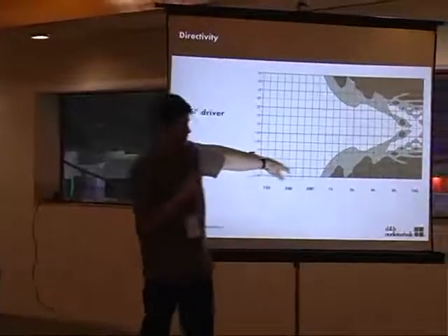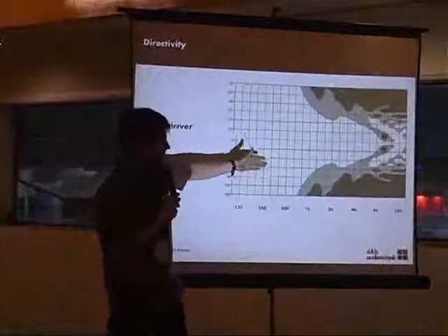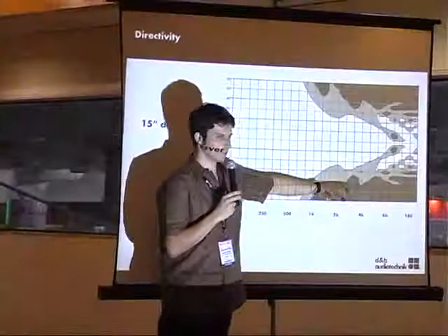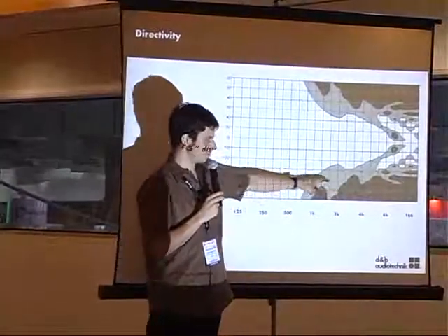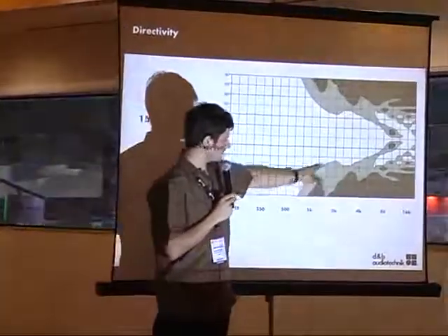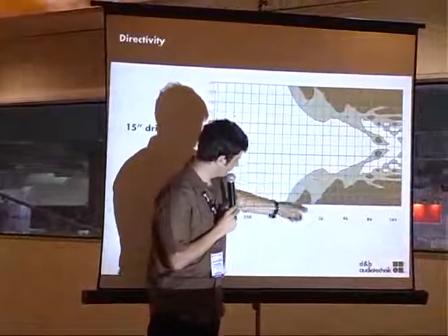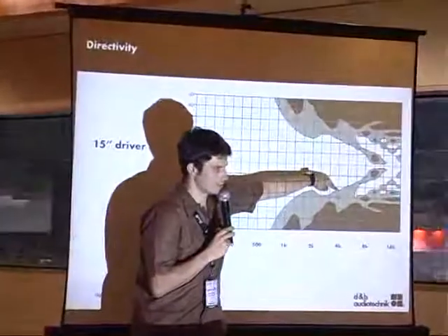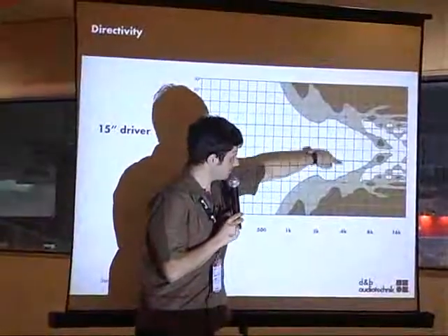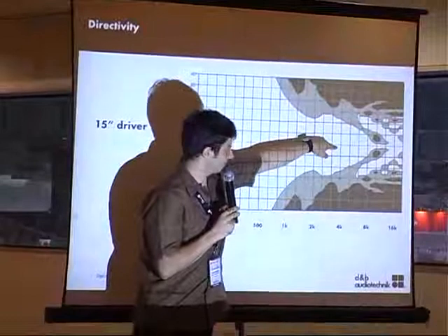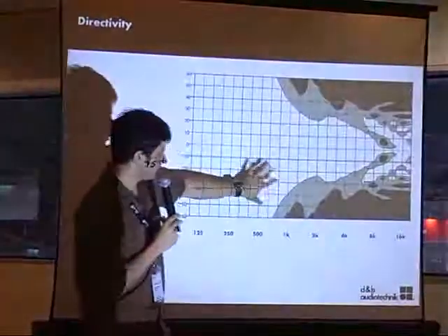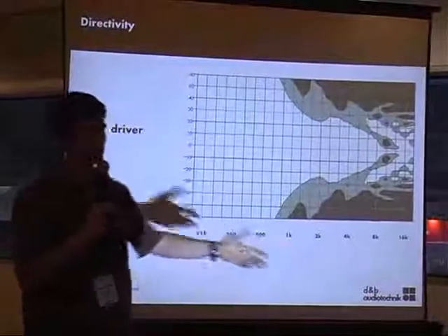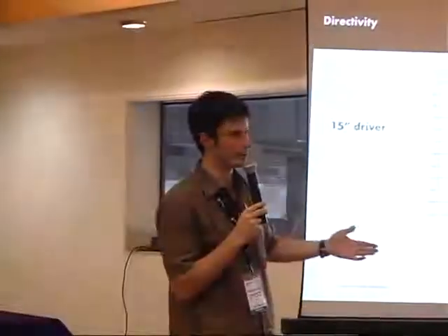And if we do that for all the frequencies, we can also do that two times to find not only the minus 6 dB point, but also the minus 12 dB point. As soon as we do that, we get those lines of transition. So for 4 kilohertz, for example, this is the angle off axis where the level has dropped by 6 dB in comparison to the level on axis. And the line that separates the white from the light gray, this is our isobar. As in Greek, iso, equal, bar, pressure, so this is our line of equal sound pressure.